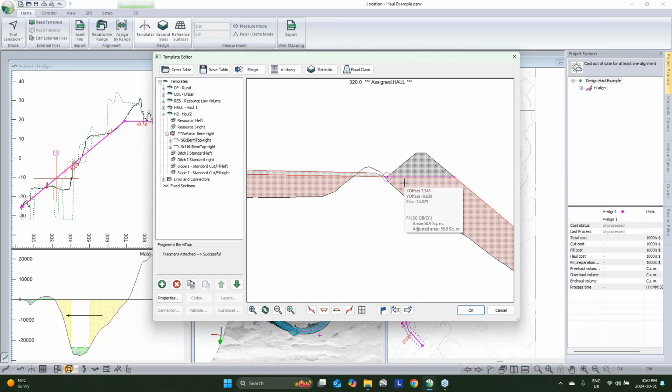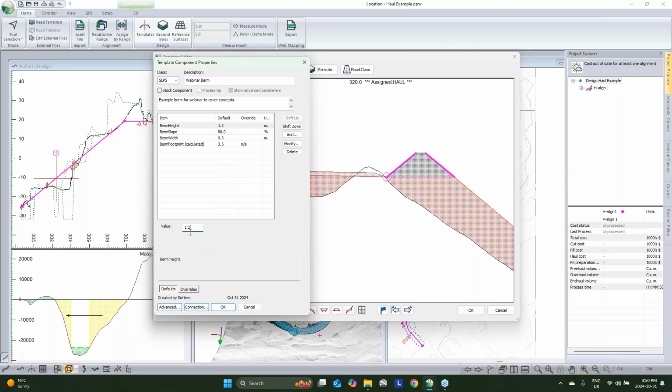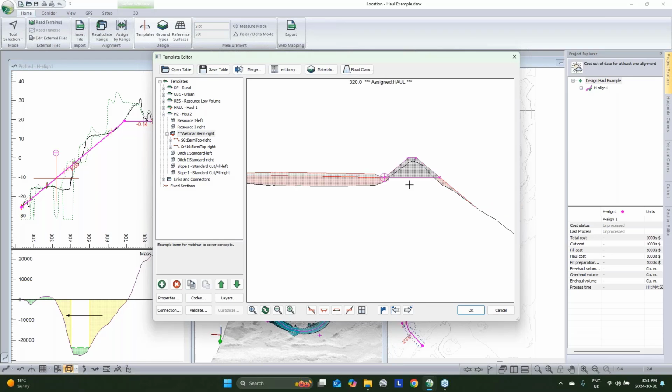order matters. So in that kind of incremental steps of complexity that we've added to it, instead of just having a single material type component, we've got a 2 material type component. And instead of figuring out each time how wide our berm is, if we say change the height, well, it's automatically being adjusted for us because this width is an expression. So we can keep running with this, and I'll try to be somewhat cognizant of the time, but let's add a little logic in here.